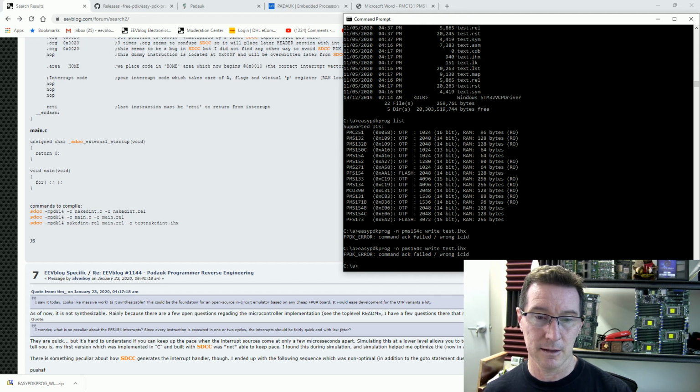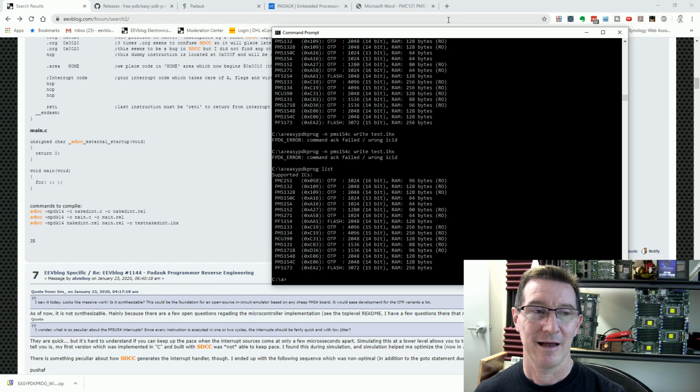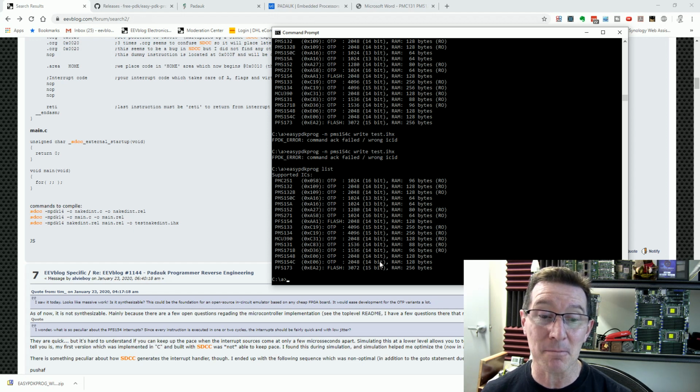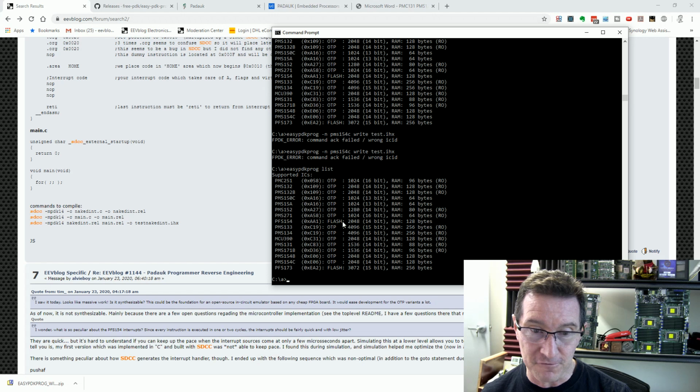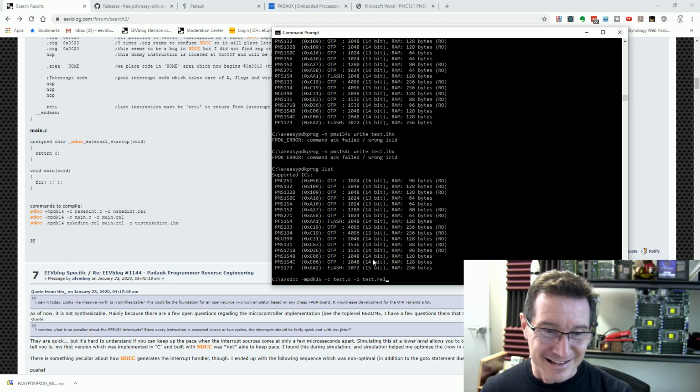No. Okay. Definitely put in a 154C. Aha. People are probably screaming at me. Dave, look down this column here. The PMS 154C is a 14-bit, in brackets. So there you go. I assumed, you remember how I said before, I assumed that the 15X series would be the 15-bit. It's 14 bits. And the 154 up here, which has the flash, they're all 14 bits. So I need to recompile again with the, here it is, with the 14, right? That's probably why. I can only assume that's why.